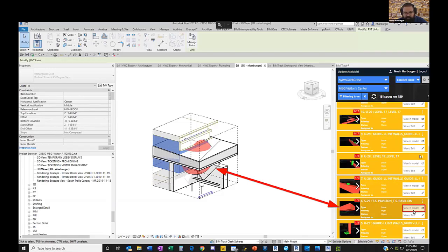It'll put this red translucent sphere over the place where the issue is. I've created, you can see at the bottom there, a work set dedicated to those spheres. So while I'm reviewing things in Revit, I'm on that work set. So when it generates these clash spheres, it puts them all on that dedicated work set. The add-in creates the spheres? Yes, the add-in will create the spheres. That's interesting that they're actually three-dimensional modeled elements. Yeah, so it generates them when you do it.